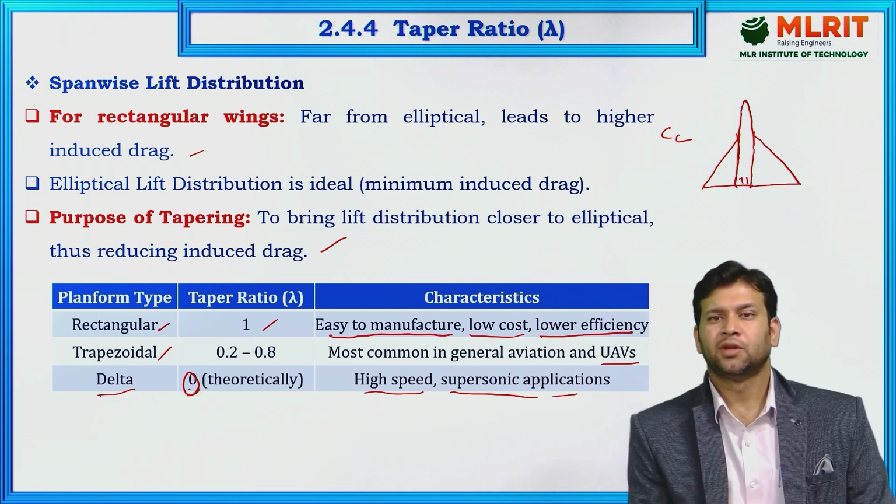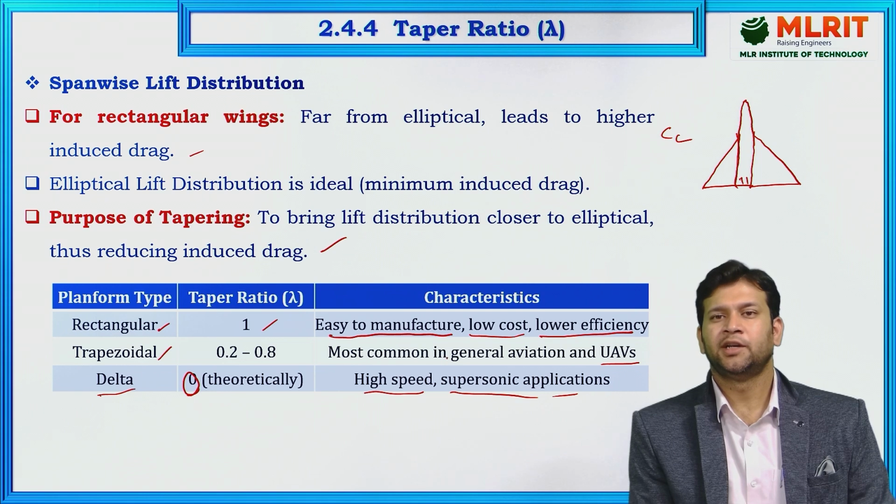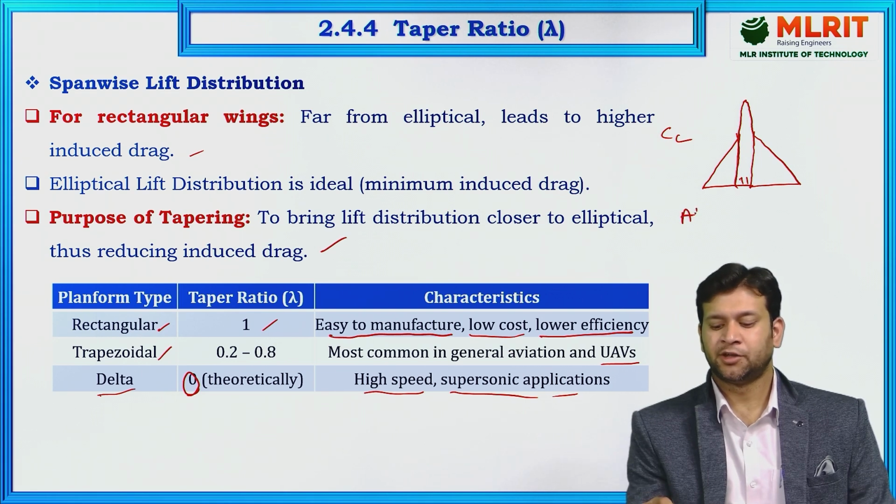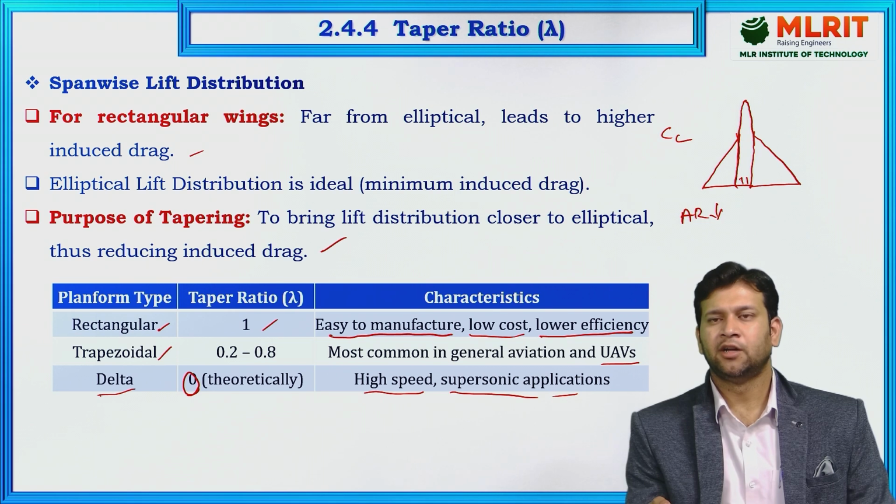The best part is they are high in speed, and it is having very good applications of higher speeds, and also the aspect ratio is lower, which leads these kind of wing structures ensuring that aircraft can go for random pull-ups, pull-downs, and vertical climb, vertical dive, spiral pitch up, spiral pitch down. These all categories are attained using delta wing configuration.